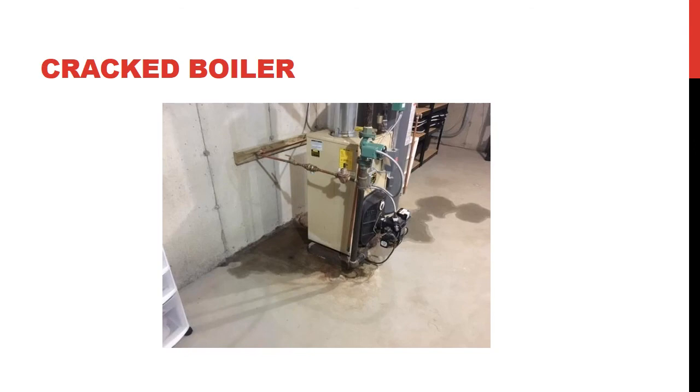Sometimes the leak is not that big, so it can leak throughout the entire season. But when you have a leaky area like this, you want to know where the leak is coming from. So it could be you have to remove all the casing and check where the water is dripping. From looking at this, it could be from these valves, it could be from the casing itself. So you want to remove it and keep it running and see where it leaks. Sometimes the boiler does not leak when it's cold. You have to heat it to see where the leak is coming from.